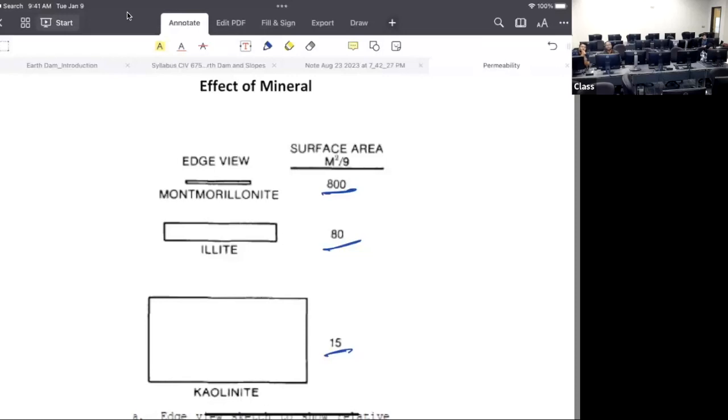Because of how you create your samples in the lab, in ideal conditions. You have the sample, you break it down, make it like powder, and then you add the lime, another powder, and mix it together. Then you add water, make it like a dough, and compact it inside your mold. So all the results are great, right?